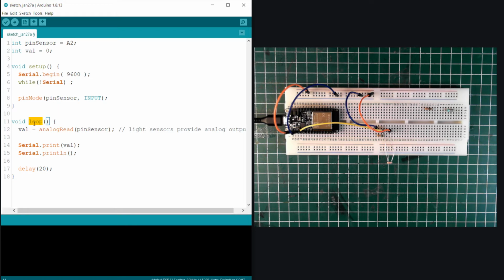light in a sunset. So what we do is limit this rate, and this is equivalent to saying, 1 second has 1000 milliseconds. If I divide this by a 20 millisecond pause, which is what the delay does, this will give you approximately 50 readings. Is that 50? Yeah, 50 readings a second, which is what we are after, a maximum of. So we know that this sensor is in particular going to give us 50 readings a second.